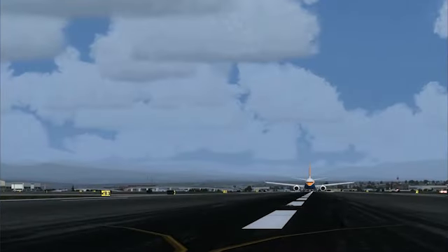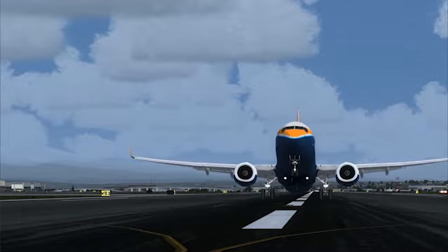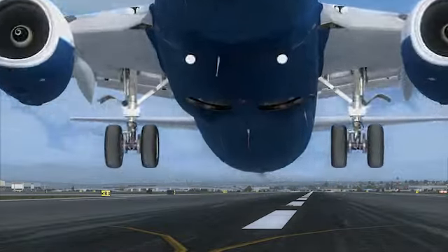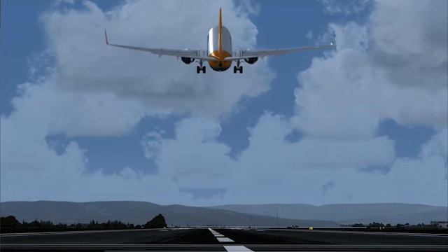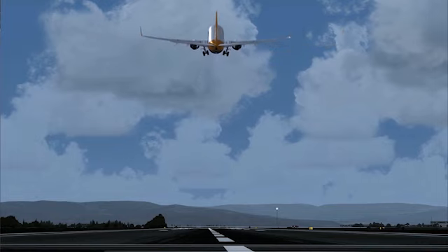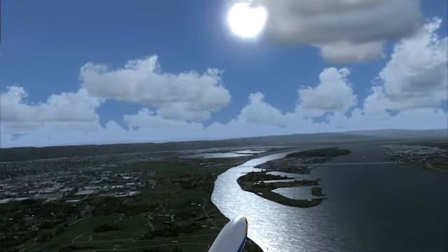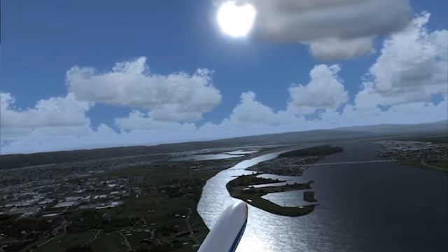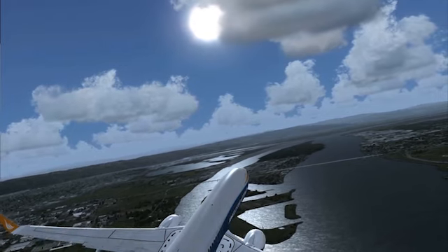Autopilot operation in and of itself is pretty simple when one can gain an understanding of the flight director. It appears as though the autopilot is simply following the flight director commands once engaged. However, as mentioned before, the actual data used varies a bit. Regardless, once you gain an understanding of the MCP mode selection, the modes displayed on the flight mode annunciator, and the fact that the flight director is giving you commands to follow these modes, it's easy to understand that the autopilot, in basic form, does the exact same thing.